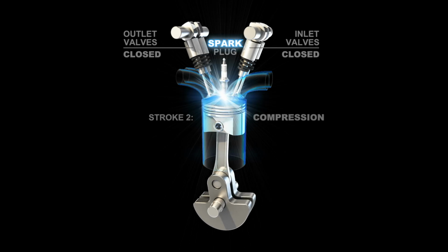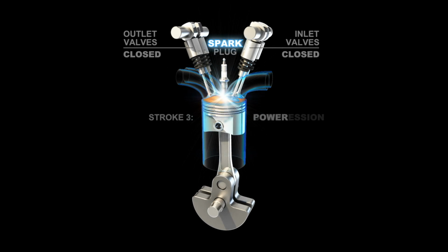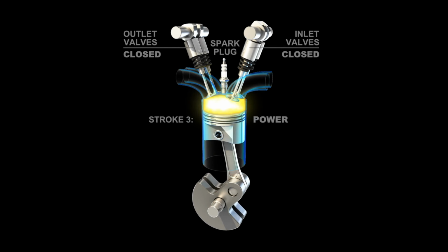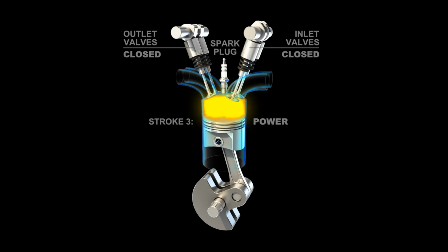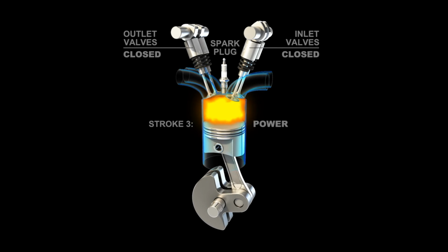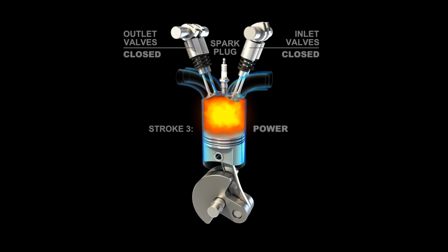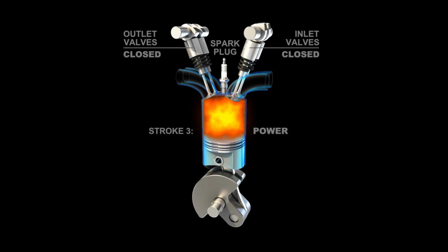And then as a result, the spark event happens, the piston starts to travel downwards on the next stroke, the combustion stroke, towards bottom dead center. And we can see that's going to create a huge flame front and a pressure wave that's going to help that piston and rod push downwards on the crankshaft to produce more horsepower and torque out of the engine.